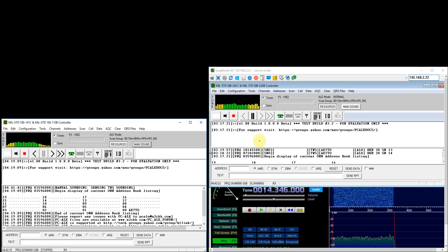Now, I should have mentioned that one of the reasons it wasn't received is because this receiver has a bandpass filter on the input to that software-defined receiver. That SoftRock has a bandpass filter on the input that pretty much limits it to the 20, 30, and 40 meter bands. So I just tried to send it a signal on the 80 meter band, and not surprisingly it wasn't received. So let me switch to a more acceptable band.